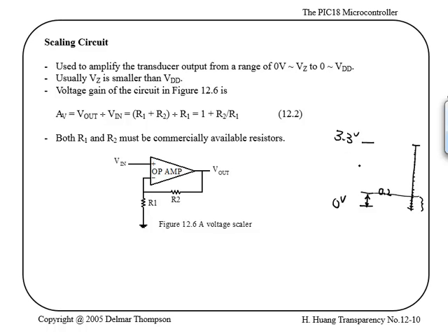So a full signal from 0 to 3.3 volts would give you from 0 to 1023 values, right? A signal without conditioning, without any changes from that sensor to the PIC pin, if you don't change that, then essentially you're going to get only the range from 0 to 1023 times 0.2 divided by 3.3, right? Much fewer values. So your resolution is not going to be 10 bits, it's going to be much less, right? So if you don't want to do that, one way of doing it is to condition the circuit.